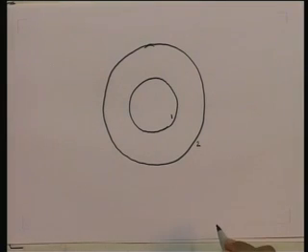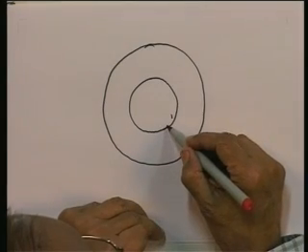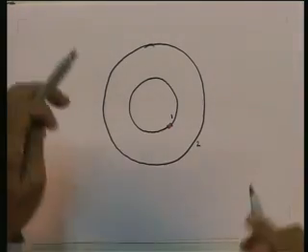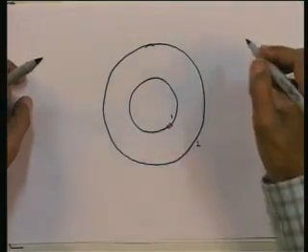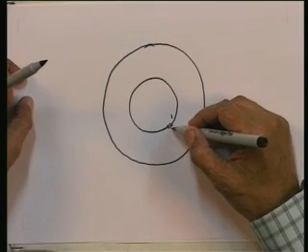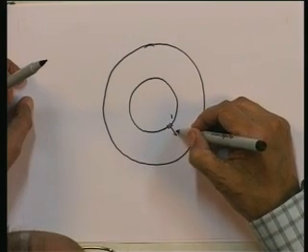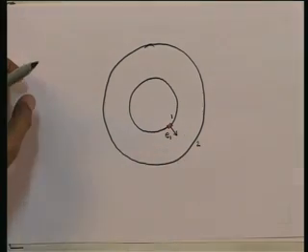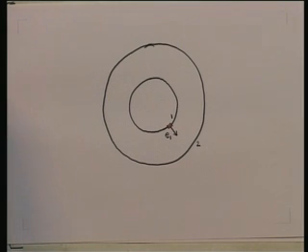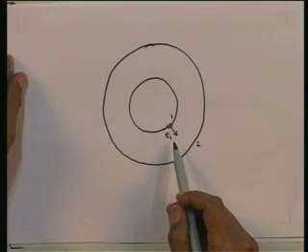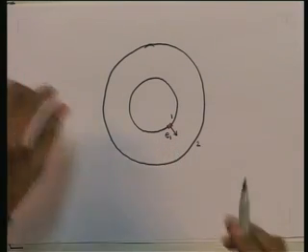Consider now the radiation emitted from some element on the surface 1. Let us say I have some element on the surface 1 and we consider radiation emitted from it. The emissive power of surface 1 is E1. So, let us say symbolically that E1 is what is emitted, E1 so many watts per meter squared is what is emitted from this surface. E1 will be given by epsilon 1 sigma T1 to the power of 4 by the Stefan-Boltzmann law.